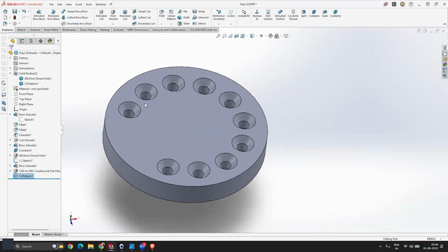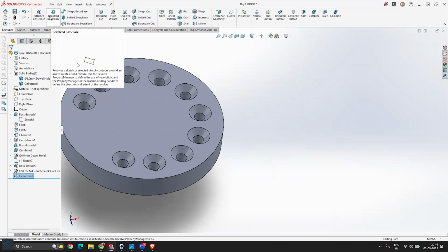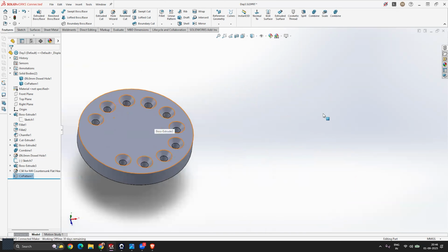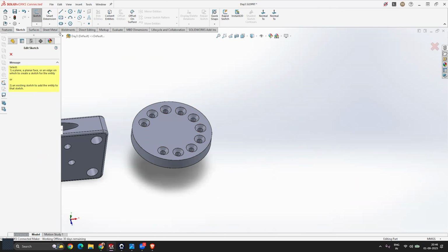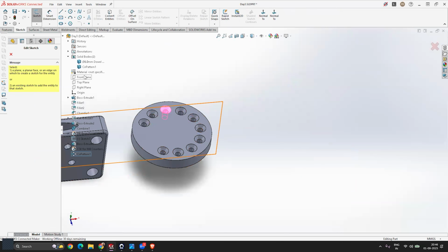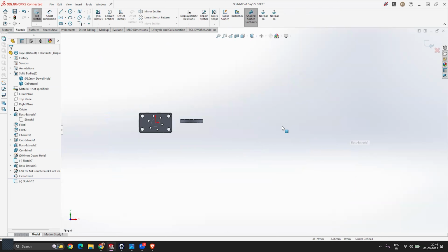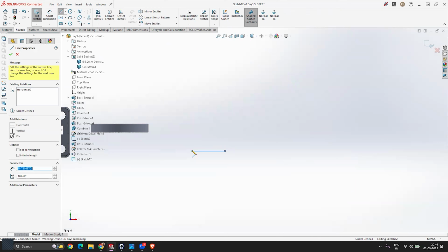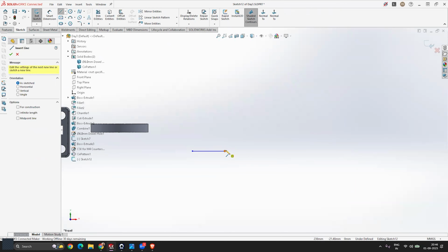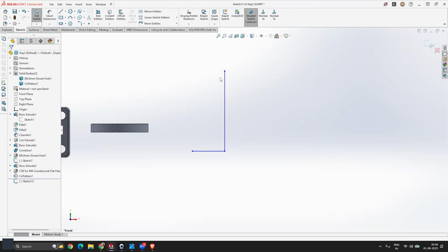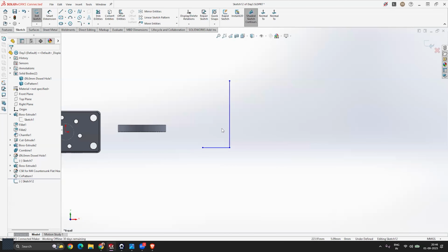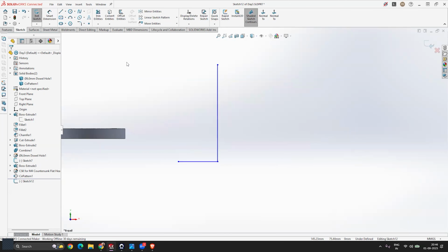The next tool on our list is this revolve or sweep tool. It's a very simple tool again. Let me create a few sketches. We'll activate the sketch tool and go onto the front plane to create a sketch. Let's create a straight line first, like this, and a line like this. So what I did, I created a horizontal and vertical line, very simple lines. Now let's play with the spline tool and see what we can do with the spline, right?